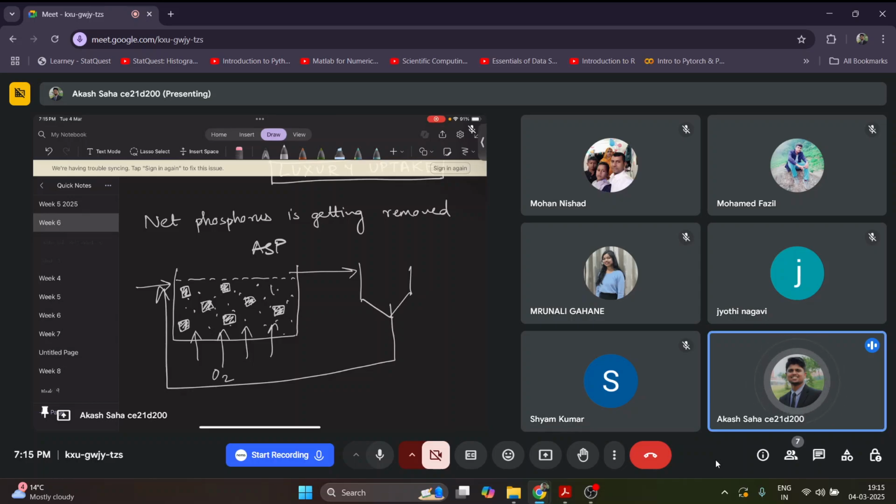So what will happen is these carriers will freely move, and on that the bacteria will attach. So now the surface area of bacterial attachment is increasing because we are providing these plastic carriers or whatever media in the system. In this way, the surface area is increasing and a smaller amount of bacterial mass is going out from the system. So recycling is also not required in the system, and the system efficiency will increase.